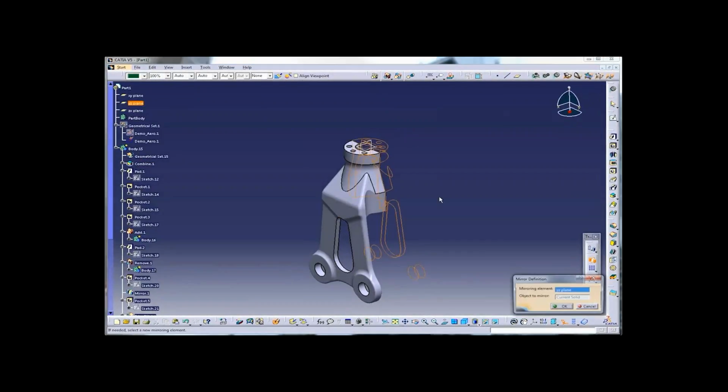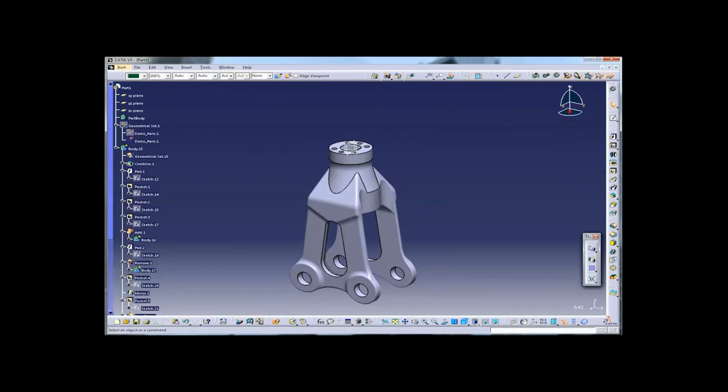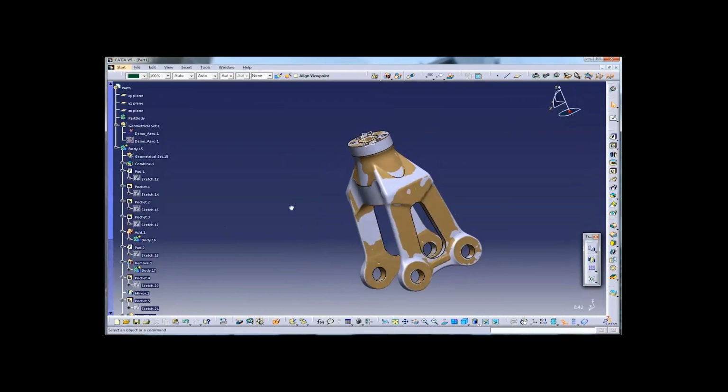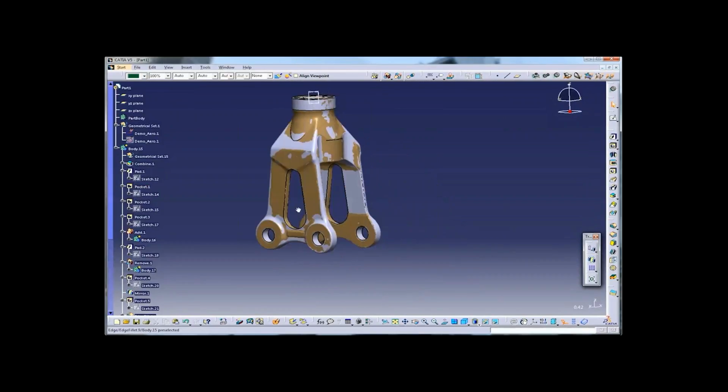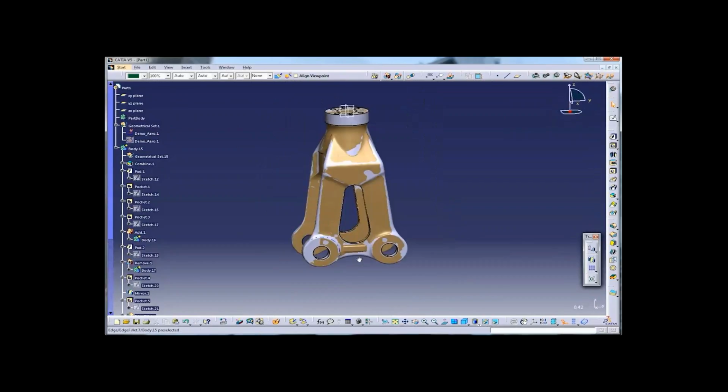All right, then we have our first half. We're going to mirror this first half on the other side, and we get our final CAD model. So, a parametric CAD model that can be re-edited as you wish. Okay, so we can take a look at how well it's overlapping our scan data in brown right now.